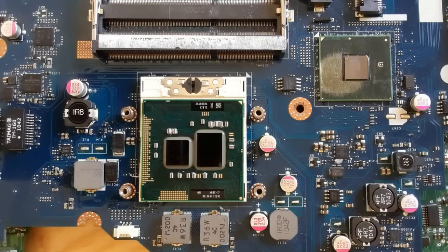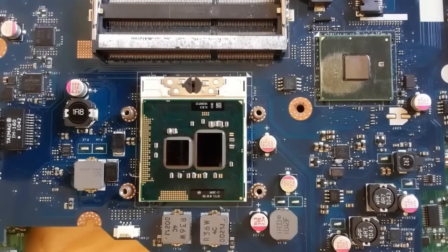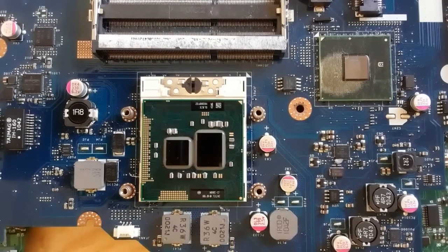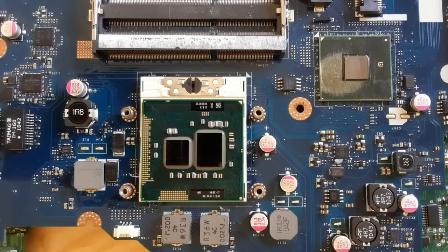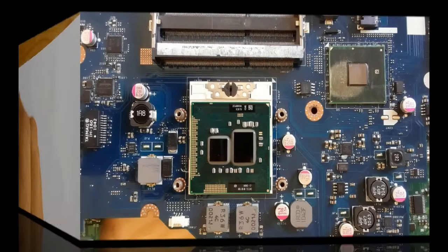So you should discharge this electrostatic or this residual current by removing all sources of power. For the laptop, you should remove the battery and the adapter and also the CMOS battery, and then press the power button for about 13 seconds and then release it. Then put back the CMOS battery, the battery for the laptop, and if you want the adapter, and switch on the laptop. So the electrostatic can cause a failure in a laptop.